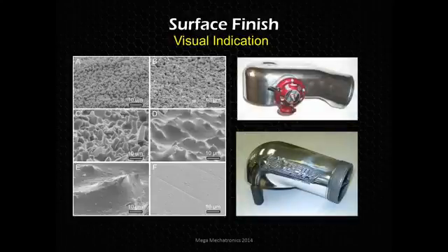So let's look at these blower bonnets. You can tell the top one here is kind of shiny. It's not rough, but it is a little dull. So we can sort of assume that it's not exactly rough, but sort of in between. The peaks and valleys are smoothed out. So maybe something like D there, delta D. But then we have this very highly polished one, and these are both aluminum. You see that this polished surface, that mirror finish, is very, very smooth, something like you'd see in that F image there.